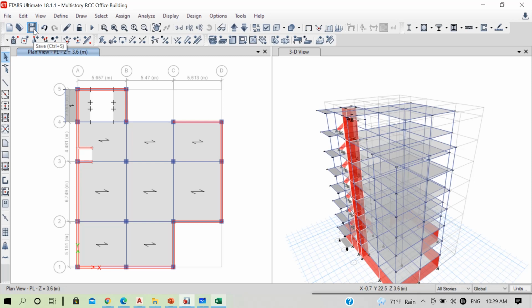Now after completing this, let's go to assigning loads. We created different types of load patterns in our previous lecture, including dead load, different types of live load, floor finish, masonry, partition, swell pressure, and water tank load. So first let's apply the masonry wall loads.